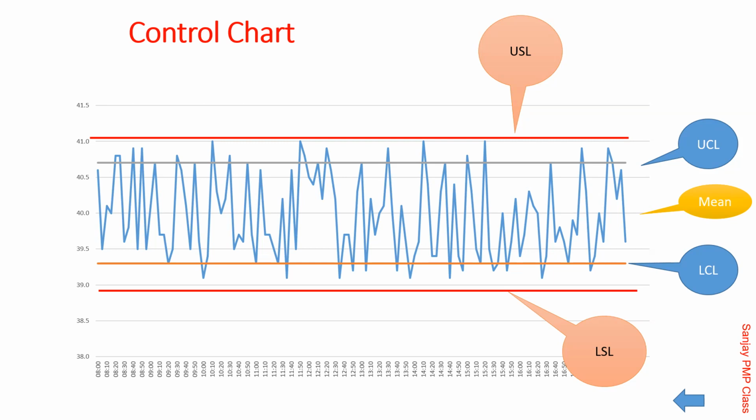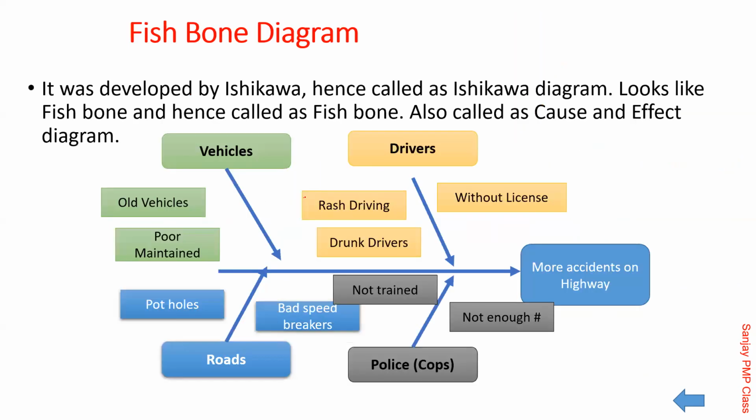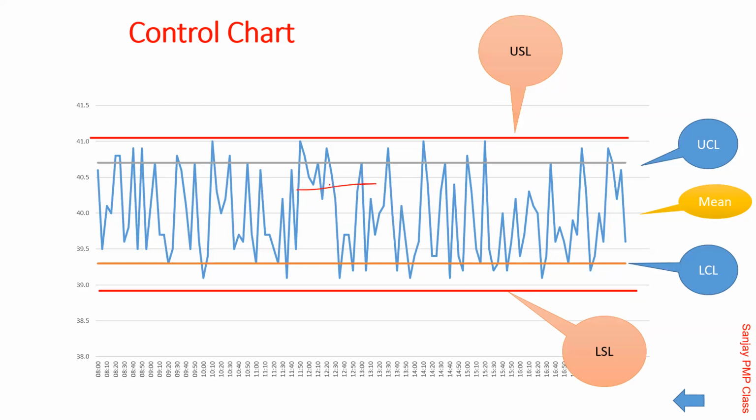Okay. See, typically here, one important thing, friends, try to understand. As Sanjeev is saying, if it crosses the upper control limit or the lower control limit, either lower size or higher size, something has gone wrong. You need to immediately stop it because if you continue, you are going to cross that. But this theory says that even if you have not crossed it, and 7 points are all above the mean, or 7 points are all below the mean, 7 consecutive points, now they say stop it.